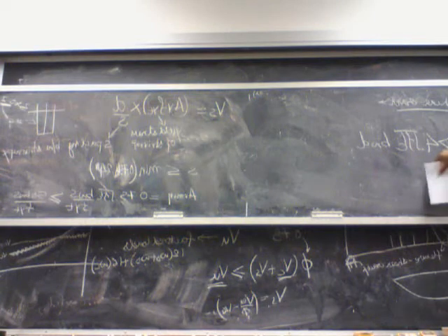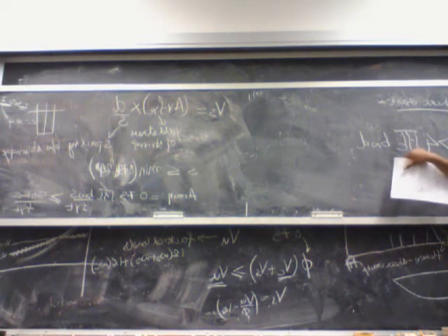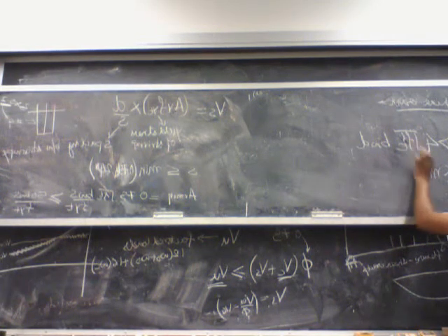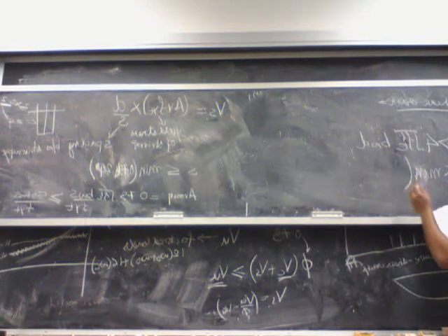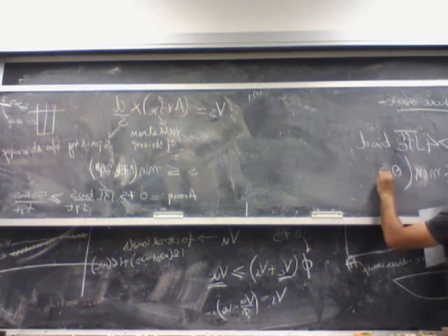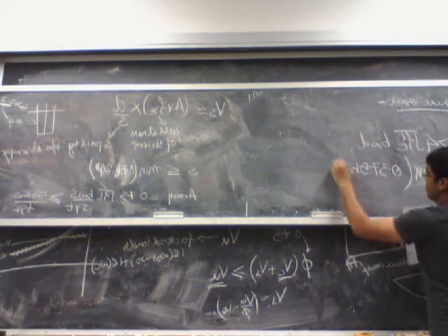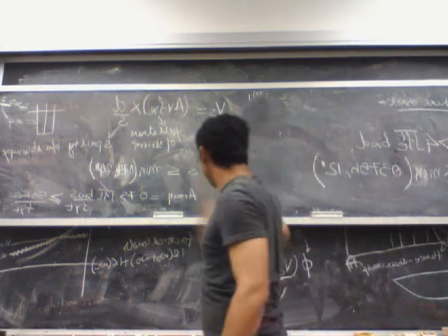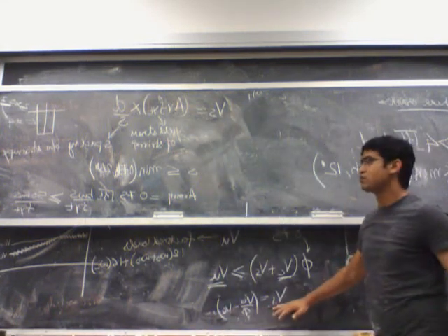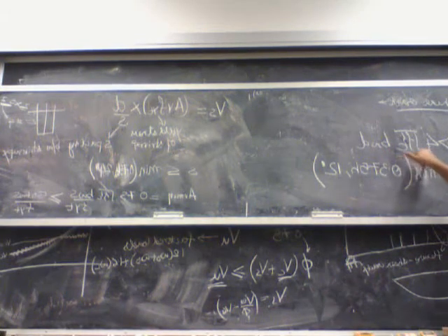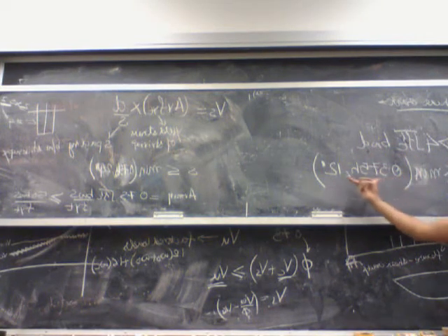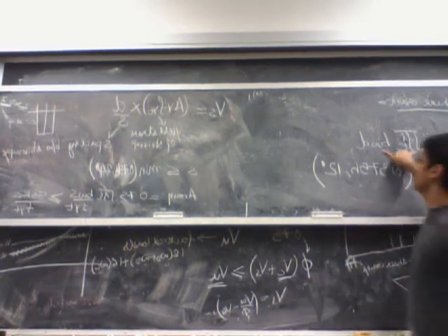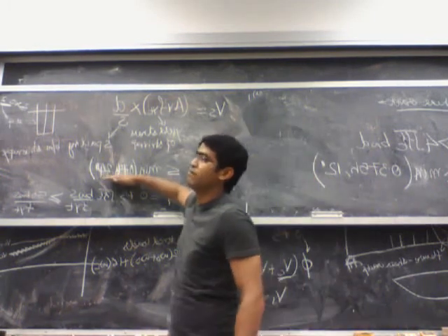And in case your Vs comes out to be more than 4 times square root f'c b_w d, then the maximum spacing is the minimum of 0.375 h and 12 inches. So you calculate the value of Vs from this formula, and if this Vs is greater than 4 square root f'c b_w d, then this is the limit on the maximum spacing. If your Vs is less than 4 square root f'c b_w d, then you have a different limit on the spacing.